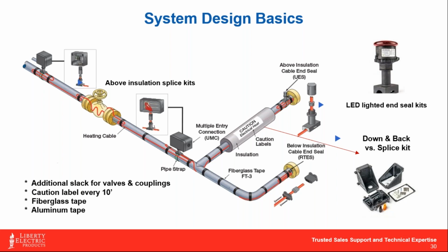And once you throw an inch or an inch and a half of insulation on there, 10 watts a foot is going to be a lot of heat. So it's nothing that may damage something immediately by any stretch, but over years of that kind of exposure, where the system maybe stays on for, who knows, 5 hours or something like that, yeah, there's the potential for that cable to build up too much heat, despite the fact that it's self-regulating. Remember, it can't really go much below its output value. So there's only so far it can go down.